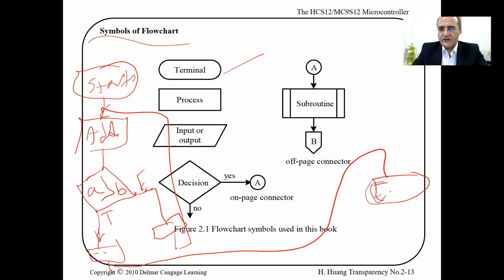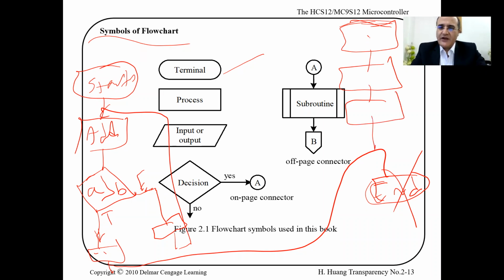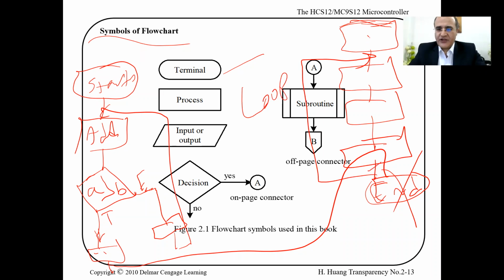A terminal, you end. The difference between software design in embedded systems and non-embedded systems is that the software doesn't ever end. There has to be an infinite loop, and we saw this in our examples, right? So if any of you draws a flow chart for a design when designing software in this course, you will have all these steps, and at any point of time, there will be an infinite loop, right? Regardless of the details, after checking a condition, you keep doing something over and over again, and there is no end. The embedded software does not end.